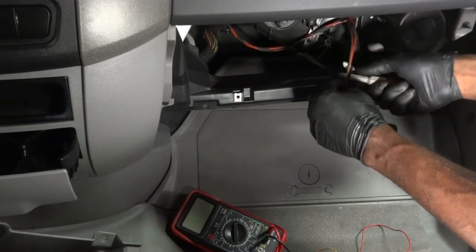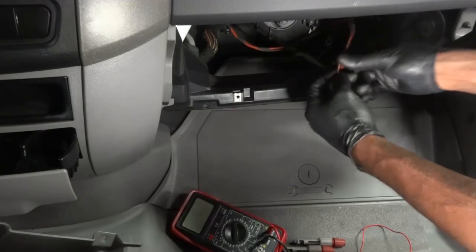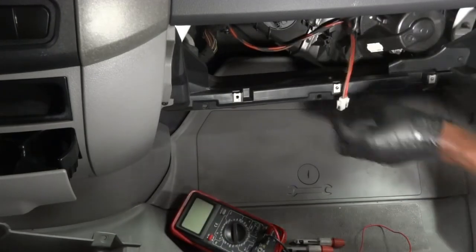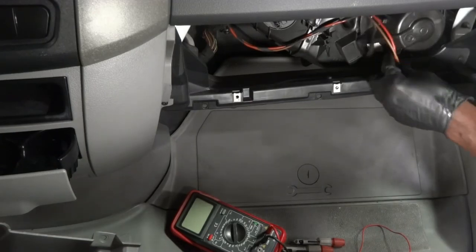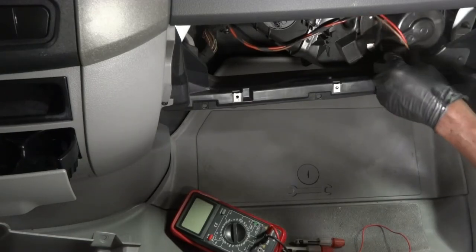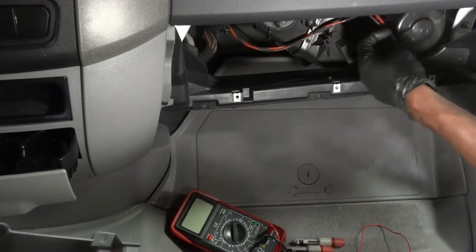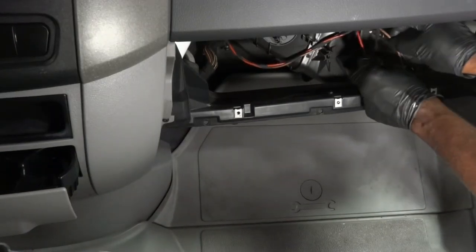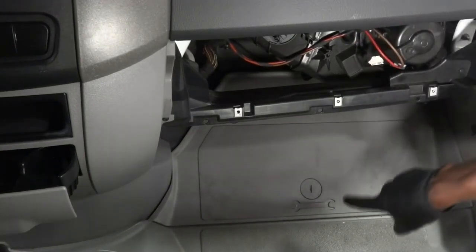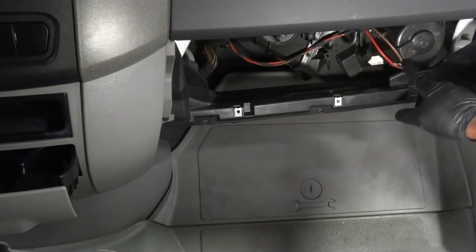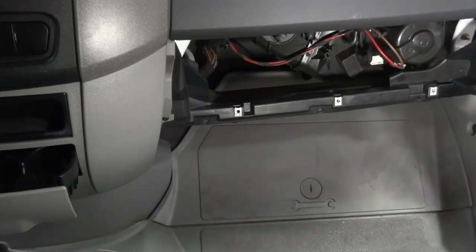So there's another test I want to do. Actually, I don't even think it's important at this point. It's a current flow test. I'm going to connect this electrical connector back to the blower motor. The electrical connector is connected back to the blower motor. So now I'm going to bring up my lab scope here, and then I will use an amp clamp around one of these wires to see if we have any current flow.